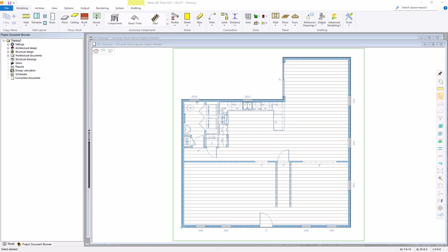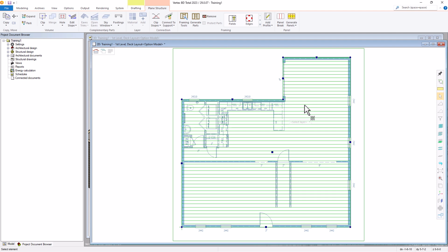We can also edit a floor boundary very easily. If we select a floor boundary, you'll notice that it is made up of endpoints and midpoints. Circles are endpoints, and between every 2 endpoints, you always have a midpoint. You can left click on a midpoint and stretch the entire edge or segment.